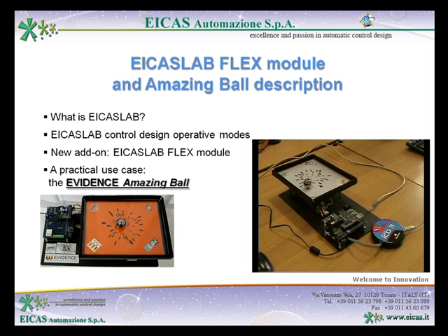Amazing Ball is a complete, ready-to-use system for learning and teaching real-time automatic control. It consists of a steel plate pivoted on a central joint. The system has 2 degrees of freedom, ensured by 2 servos connected to the plate, with a high-resolution touchscreen that measures the coordinates of the ball mounted on top of the plate. A Flex Demo 2 board controls the hardware using ERIKA Enterprise.